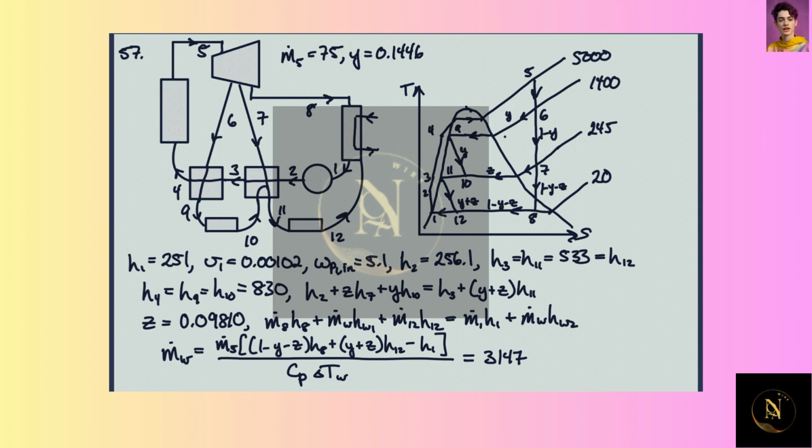Then at the 6th point, we have 6 going to 9, so it cools down, and then it condenses while it's giving up heat. You can see that we have these temperatures here are the same, which is where inefficiencies would happen, because you wouldn't really have the same temperature coming out here, because you wouldn't get a perfect transfer of thermal energy here.